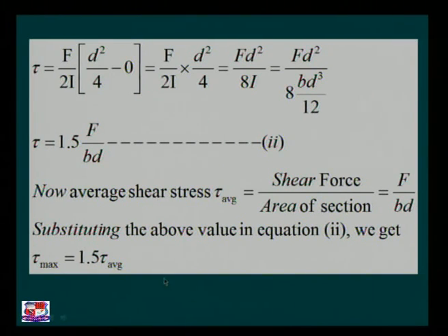So if we know the cross sectional area and the shear force at a particular section, it is easy for us to find out the maximum value of shear stress along a rectangular section, as we already know that the value of shear stress is 0 at the top and bottom fibers. So with this, let us solve certain numericals related to this.